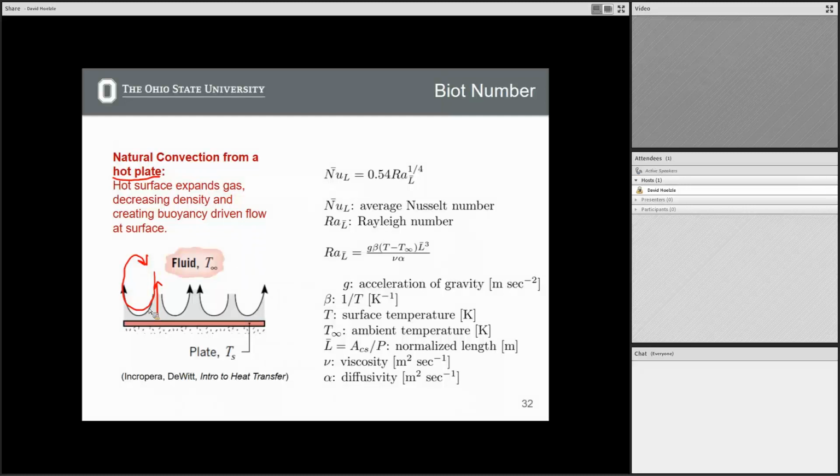So to derive the heat transfer coefficient for natural convection, you have to go to a textbook and look at the types of convection and figure out, all right, what is my geometry? What's the orientation of my geometry? And what are the boundary conditions that match some of the empirical relationships that people have derived over the years. This is just walking through one of those.